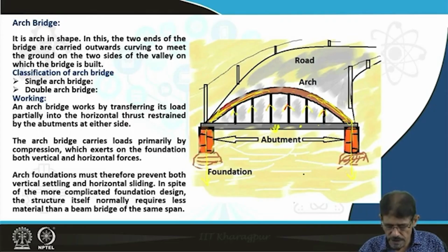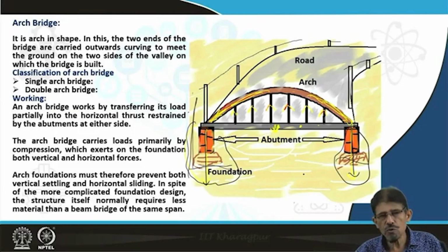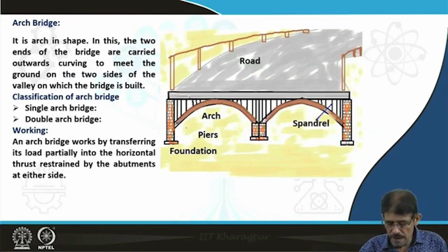Therefore, in this type of bridge, the whole load transfers toward the abutment. Therefore, the strata associated with the abutment or the walls of the valley should be very strong and of excellent category in terms of rock mass quality. Here the arch structure is in a supporting situation.